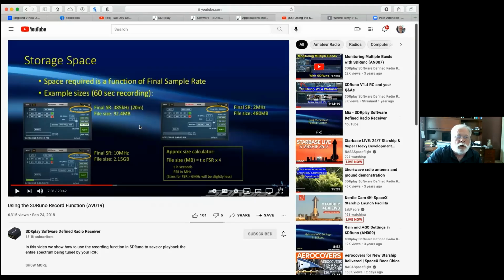Okay, so this is an example. I'm hoping you can see this. If you search our catalog for AV019, it is just a video, John. You can also search our YouTube channel and find it. But you see here, for 60 seconds of recording with a final sample rate as shown in the main window of 385 kilohertz, I got 92 megabytes. At 2 megahertz, the file size had gone up to 480 megs. With the full 10 megahertz of bandwidth, which obviously doesn't apply to this medium wave example, your file would be 2 gig.